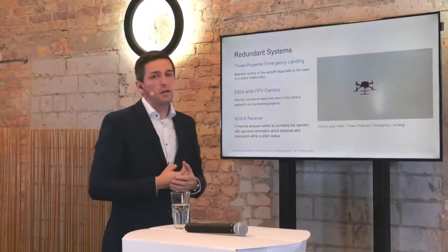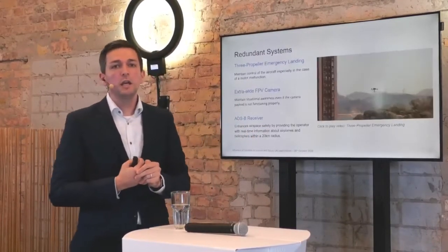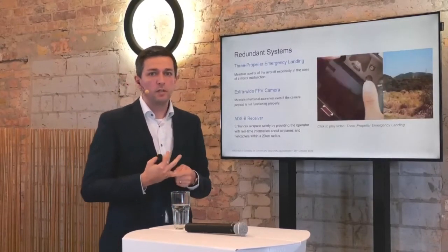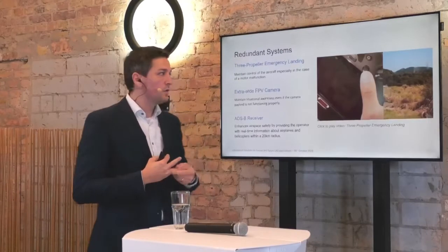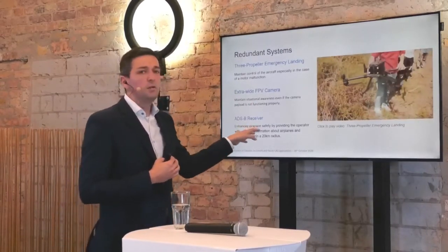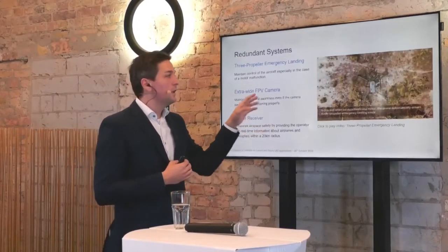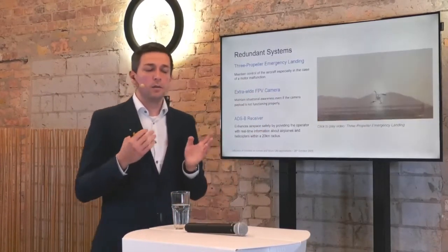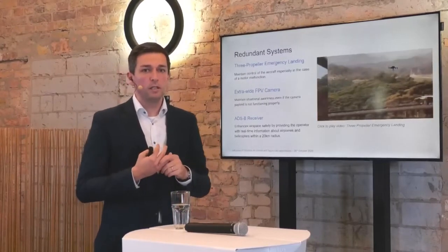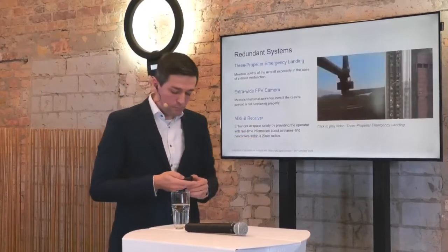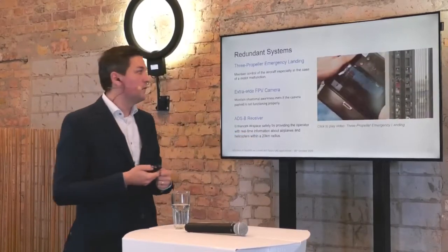And what is, I think, interesting for the aviation community, what we as DJI include in all enterprise drones above 250 gram since 2020. So the M300 has been launched on the market this year. We are including an ADS-B receiver. That means the pilot has the information if there are manned aircraft around, giving their information with ADS-B out. So the drone itself can receive ADS-B in. Another level of safety for the pilot.